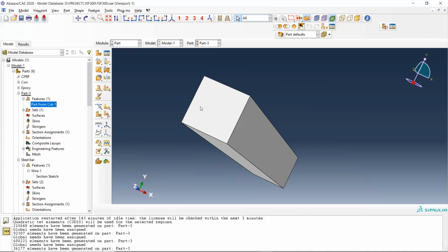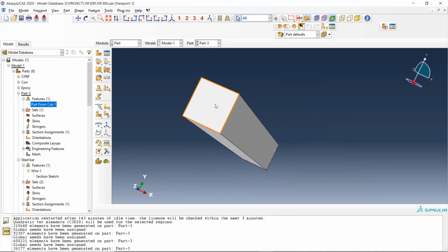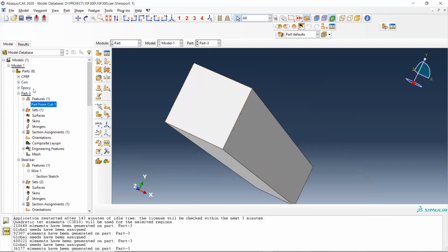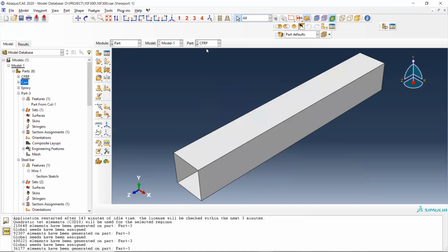So I need to do something so that I can see the holes over here also. Those holes are visible only when that is done in 3D. Yeah, you have to do it in 3D only. Later on your steel bars can be replaced with 1D, that's not a problem at all. But at least to model the holes onto this particular part, you have to do 3D. There is no choice, there is no deviation on that. You must and should.